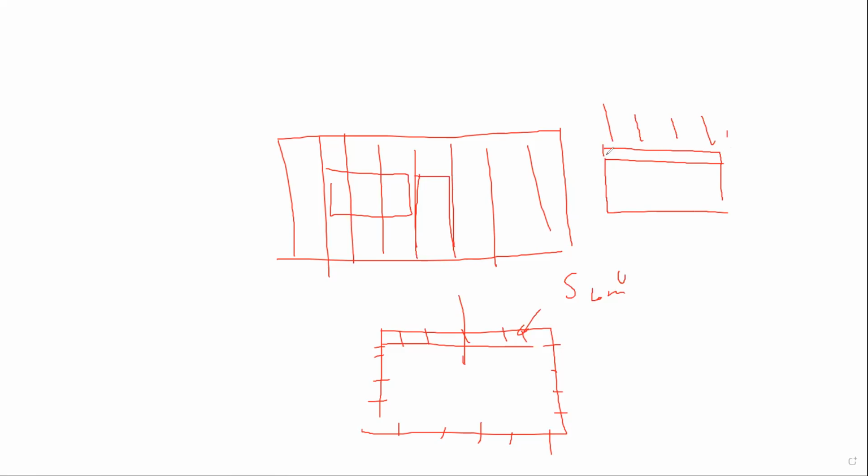And then these lintels have to be sitting on built up columns. So therefore you know what size of lumber to use for your built up columns. These built up columns are going to be subjected to an axial force from the lintel. And guess what else they're going to be subjected to? A bending force from the wind.